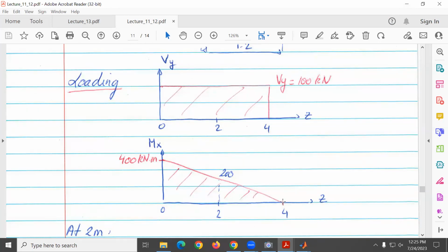Yeah, but the force is applied here at the tip. So that's what I'm saying is reverse. The measurements here are from the wall, but here when we calculate the moments, they're really from the tip, because the force is being applied here. Right. You understand what I'm saying? I thought it was clear, but did you understand what the confusion here is or not? The force is being applied here, no? So the moment will be this force times this distance, no? So really 1 is 2.1 and really 2 is 1.9. Right. Okay.